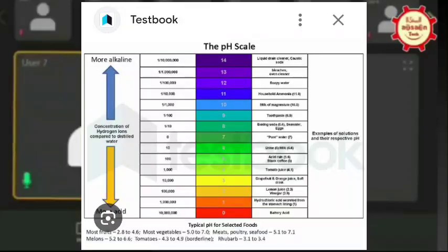But be careful that those curves given for pitting tendency or pitting resistance use a 6% ferric chloride solution. That is a very aggressive solution, with a very low pH and highly corrosive. In that solution, they may have a temperature, for stating like SDSS, of 40 to 45. But in reality, it can go much higher, based on our temperature and our chloride content.